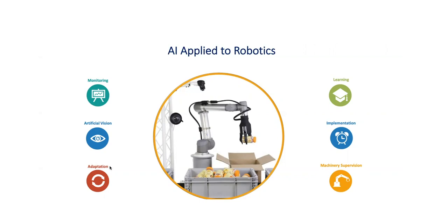Adaptation is totally related to the programmable concept. The program that we are using in the robots means that the robots can adapt their functions depending on the rhythm of the operations, or because the pots that they are manipulating are different. So if you are adaptive, the robot could be used for different purposes, not only for a specific batch. I don't know if you are working with your engineering department in the biopharmaceutical company, but every time that a new product must be set up in the line, that requires a lot of time and a lot of validation. Imagine that you can reduce this setup time between different products, because the robot can be programmed from your desktop. So the time efficiency is so huge.